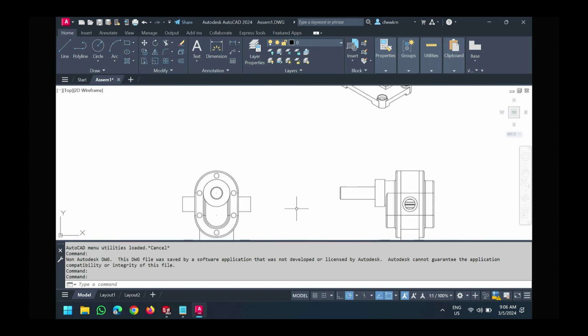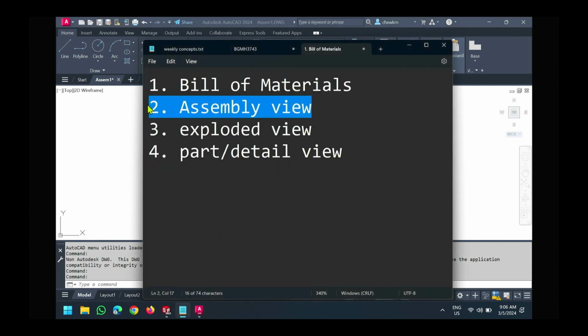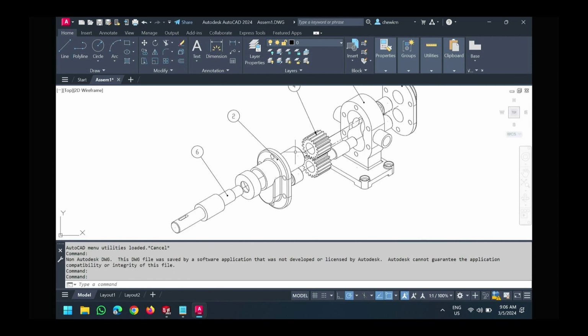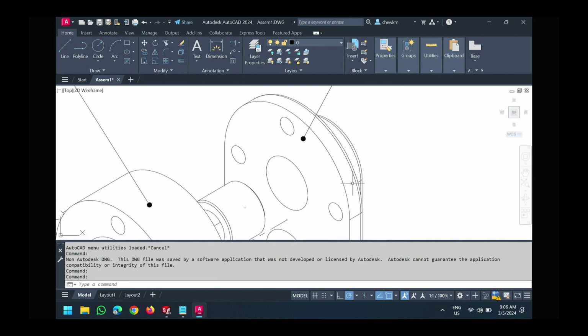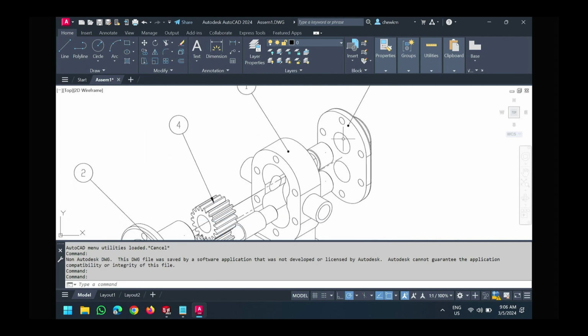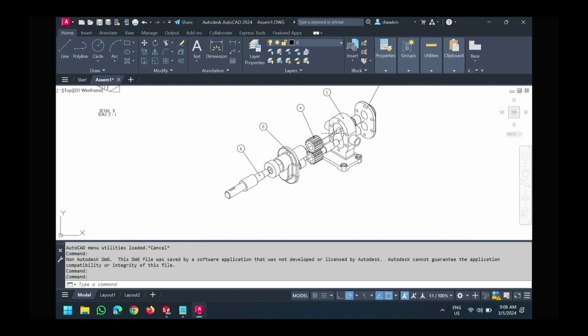So that's an assembly view. That's 1 page. The exploded view, as we know, is something like this. You've already done this. The important part of an exploded view is there must be labeling. So you have to label, this is a particular part, this is another part, and then that will tie in together with your bill of materials.